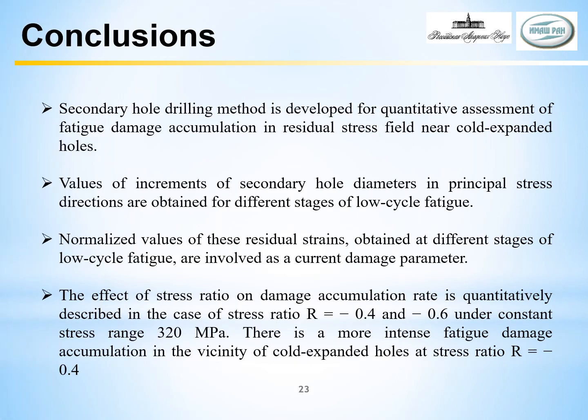The following conclusions can be drawn. The secondary hole drilling method is developed for quantitative assessment of fatigue damage accumulation in the residual stress field near cold expanded holes. Values of increments of secondary hole diameters in principal stress directions are obtained for different stages of low cycle fatigue. Normalized values of this residual strain obtained at different stages of low cycle fatigue are involved as a current damage parameter.